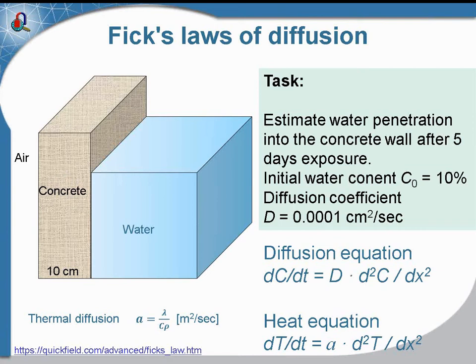QuickField doesn't have an interface to solve the diffusion equation, but QuickField can solve the heat transfer equation. You see, both equations have a similar structure. In the heat transfer equation, temperature is equivalent to the concentration in the diffusion equation.